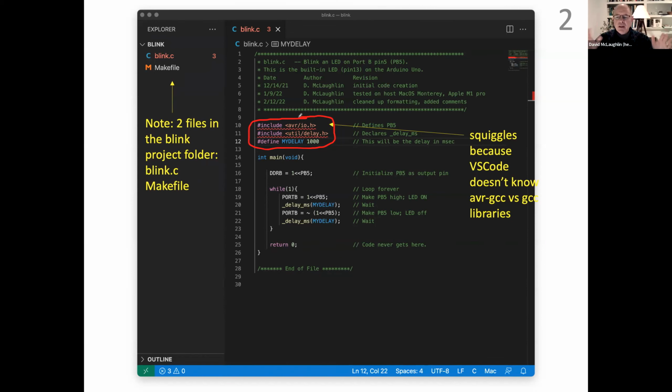Now we're doing something different with compilers. So you can delete those previous compilers if you want to get that space back. What you want to do now is download what's called the AVR GCC compiler. AVR is the name of the processor in the family of microcontrollers we're using, and you'll learn more about that as time goes on. You need to download what's called the tool chain. It's the compiler and a set of other utilities for ultimately getting C code like this translated into machine language understandable by the microcontroller. We'll talk about all that today and Wednesday and so forth.